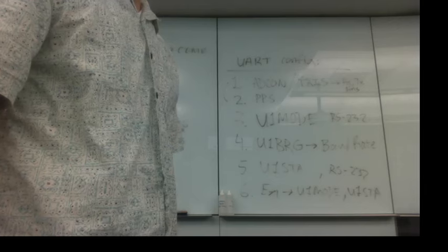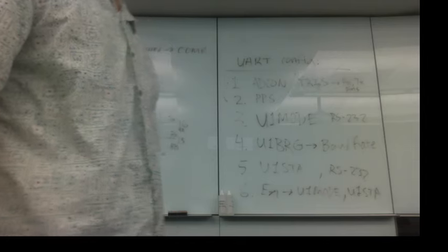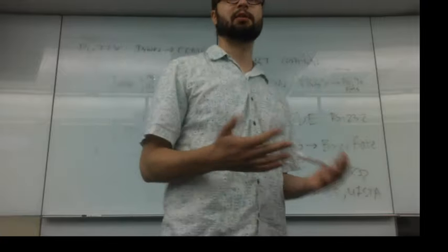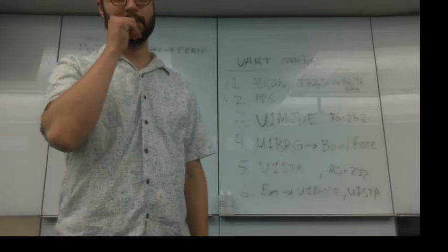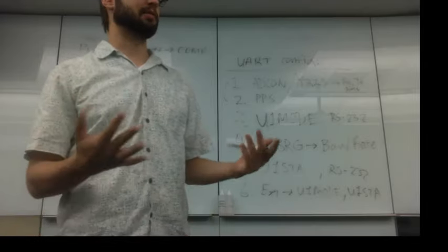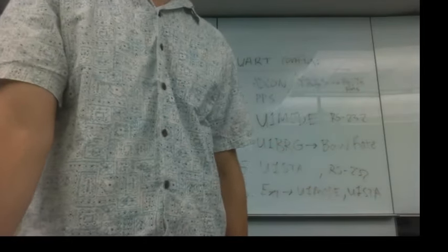TX and RX pins are enabled and used. CTS, RTS are controlled by port latches, which basically just means you can use them if you want, but you have to do it in your code to configure them, which essentially means they're turned off, but they don't say that. So we're probably going to use 00 for bits 9 and 8.